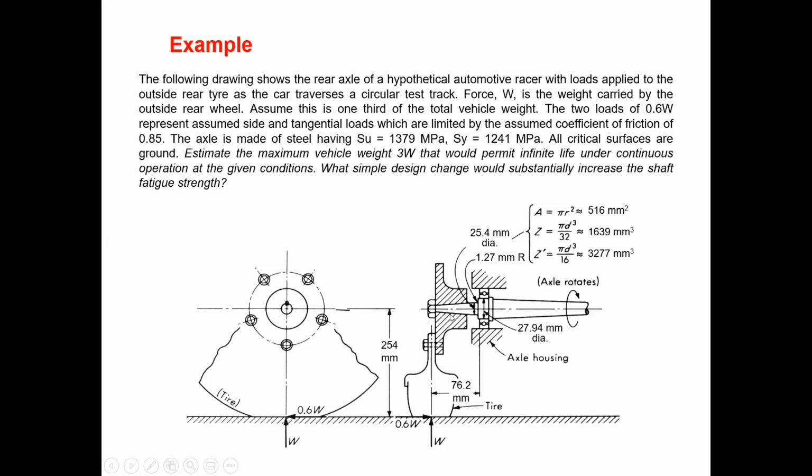So you can see here the shaft connects to the wheel, and somewhere here they mentioned the second moment of inertia and the dimension. You can see the shaft cross-sectional area will be reduced in here. So there is a fillet. Okay, so then this is the stress raiser area. So you need to focus on here, and you need to think about the load type applied in here. So due to this W around this point, bending will be applied. It will push upward.